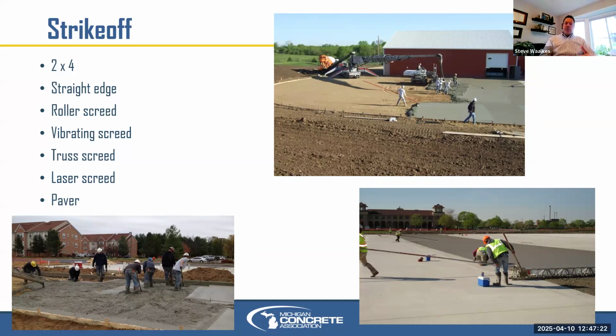So as far as what gradation and what material should constitute that gradation? Again, 21AA, on the coarser side if you could. Whether it is natural gravel, crushed limestone, or recycled concrete, they all work well. Obviously, for MDOT work, they can't use crushed concrete within like 250 or 500 feet of a waterway because of potential calcium carbonate as the water goes through crushed concrete, et cetera.